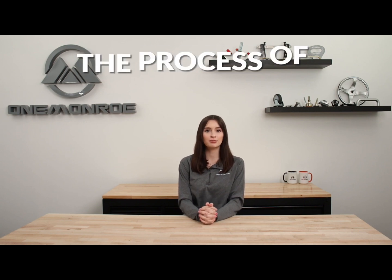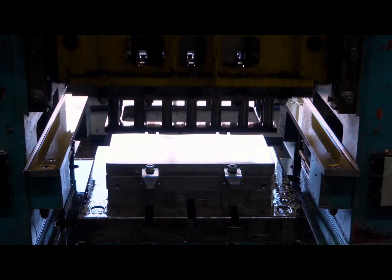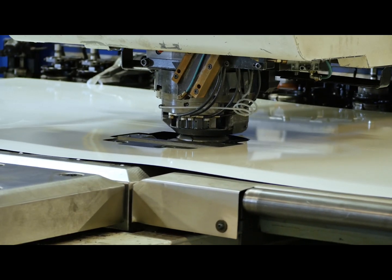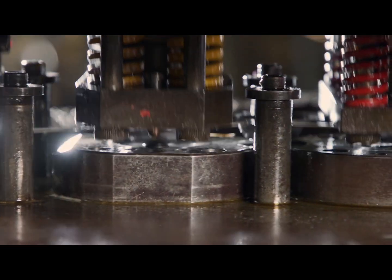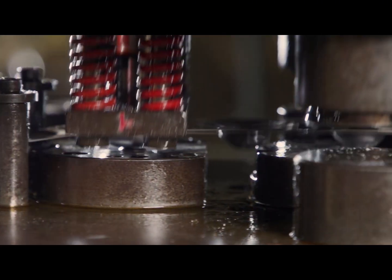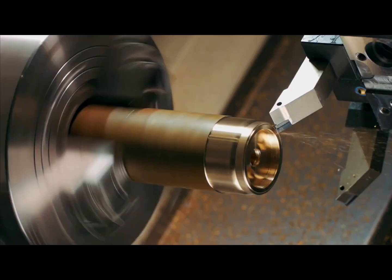Today, we're going to be looking at the process of metal stamping, some of its uses and applications. Metal stamping involves the use of a press machine equipped with dies, which are specifically designed tools that shape and cut the metal. The metal sheet is placed between the dies, and pressure is applied to form or cut the metal into a desired shape. Metal stamping can be performed on various metals, including steel, aluminum, brass, copper, and stainless steel. The material selection depends on the specific application and the requirements of the part being produced.